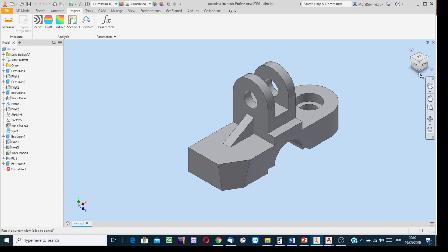Let me demonstrate how a functional dimension is shown. In my demo, consider that this channel is a functional feature. For this channel, showing its size, I'm going to show the dimension as functional. But for the others, except this one, they are going to be in contact with atmospheric air, so all the others are non-functional dimensions.